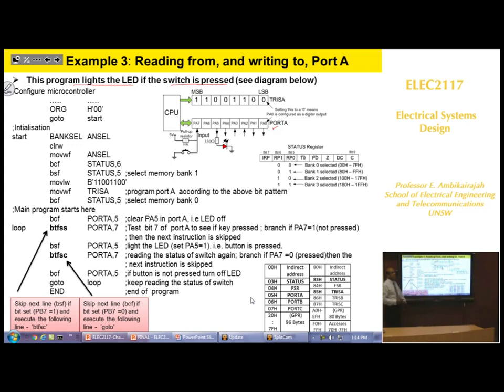I have to go back and select the ANSEL register to make sure there are only digital ports. So ANSEL, clear the W register, move everything to the ANSEL register. That means everything is cleared. That means it's digital.